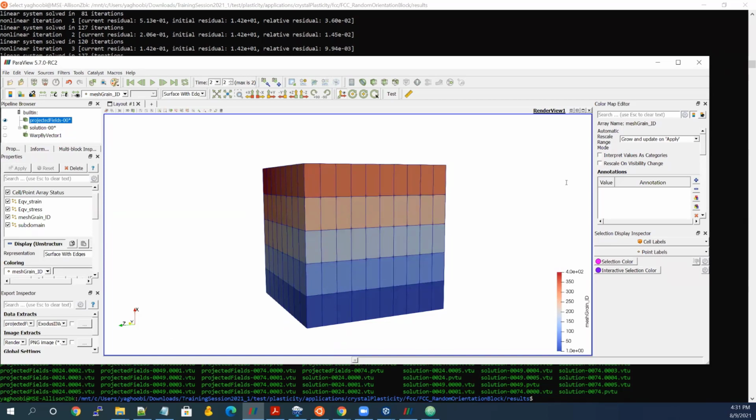Okay, so if you are trying to do the simulation, but it gives you a warning, not enough slots, it means maybe you are using too many processors. So bring down the number of processors you are using and it may work.